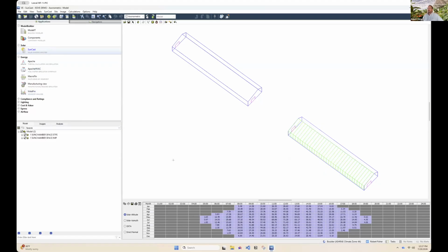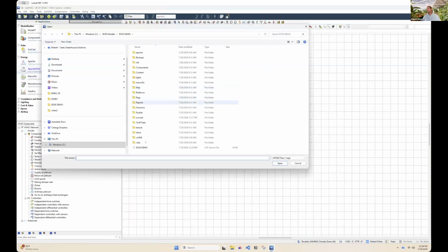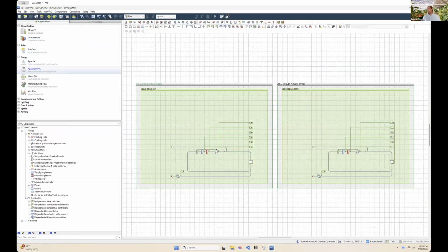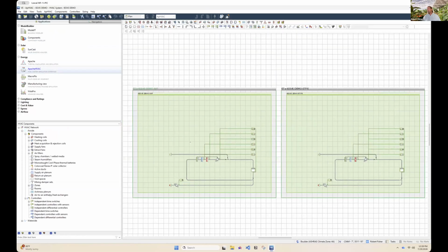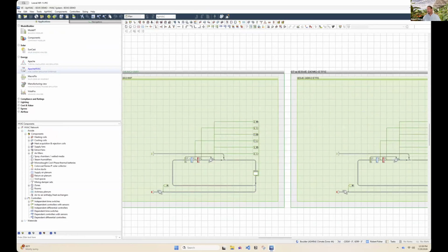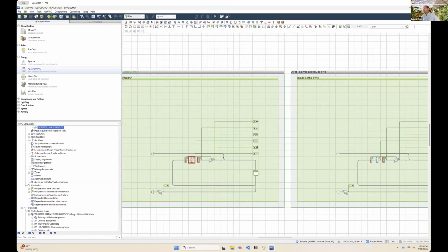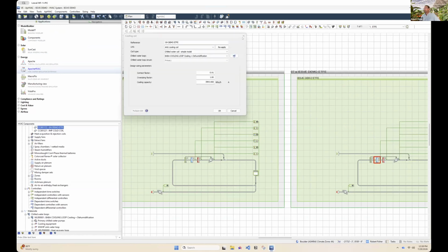Once we actually have the Suncast pulled in, you've stamped it with the sunshine, so then you can go on and rebuild the actual HVAC systems. You can build custom ones or you can pull some in. I would never really pull them in because the custom ones always seem to be what we have to do for what we're doing. Once you make the HVAC system, this is one HVAC system for the insulated metal panel building, and this is one for the ETFE building. The systems are almost the same, except the actual coils and sizes are different. This coil is actually only 907 kBTU, and then this one over here is about 3993.